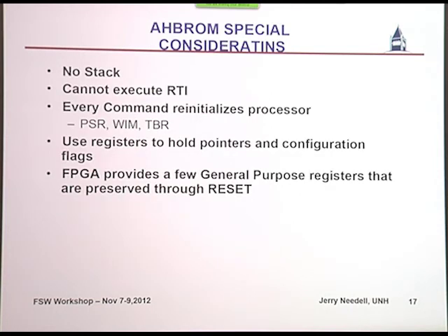But there are a few things you have to keep in mind when you're working in this environment. You've got no stack, you've got no RAM, you've got no other device, so you can't do a return from interrupt. An interrupt occurs on the SPARC, and it pushes a return address on the stack. Well, that's fine. It just goes somewhere. We don't really care, but better not try and return to it. What we do in this case is, the basic core of the system is an idle loop. You're just looping around, waiting for something to happen.